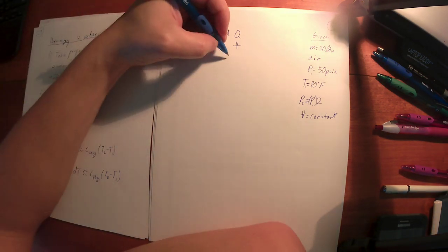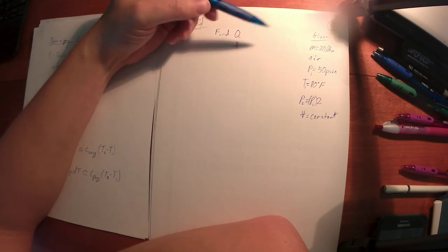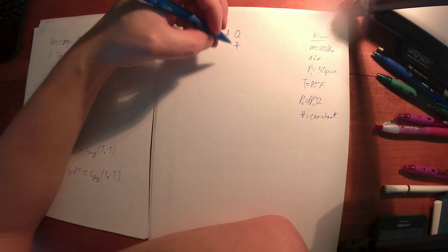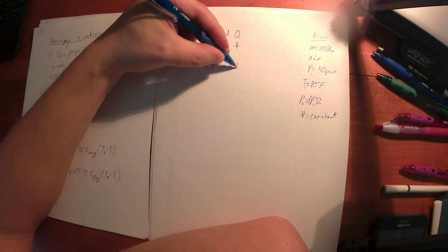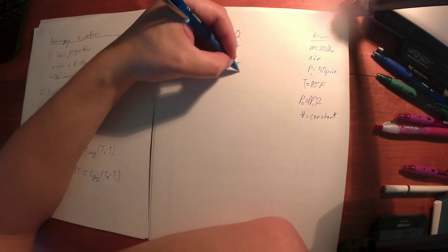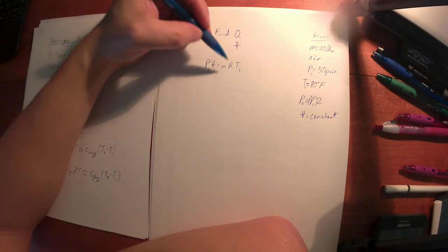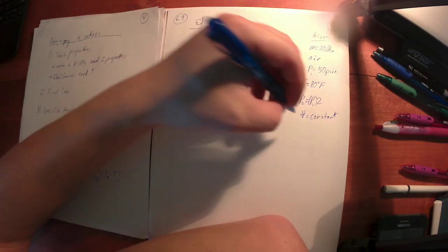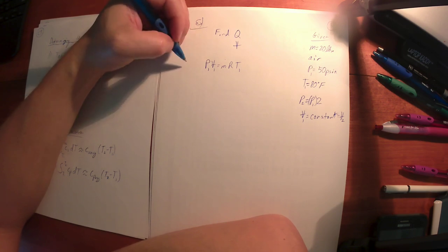Okay, so if we're trying to find volume, volume is a property. What do we know about our substance? Well, it's air. If we treat that air as an ideal gas, I know pressure and temperature at state 1. I know the mass. I can go find R. Volume's my only unknown, so that one's pretty easy. And the volume's constant. V1 is equal to V2. So I don't have to find two different volumes. Just find one volume, and that's the same. So that one's going to be easy.